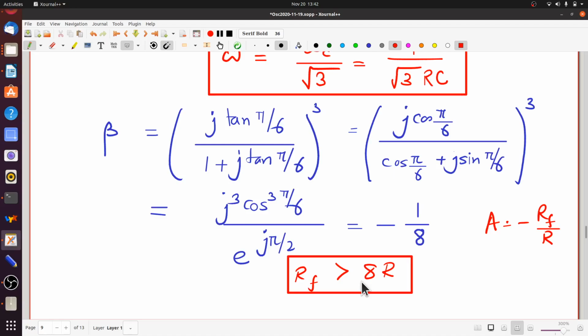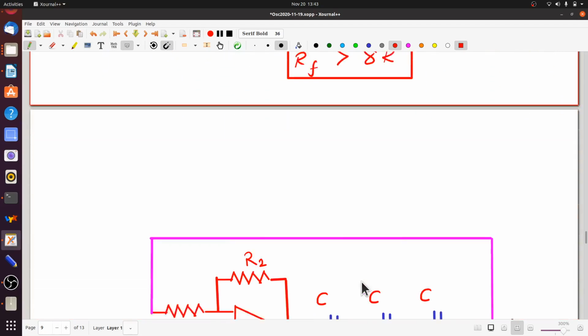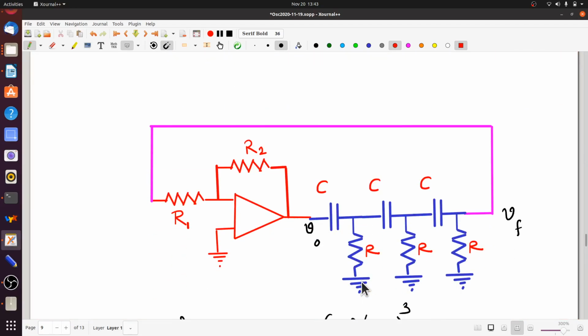But you have to notice that all we did was we had a 180-degree phase shift because of the inverting amplifier. We put in enough RC pieces to shift the phase back to 360. Well, we could have dispensed with the unity gain buffers in between and just use CR.